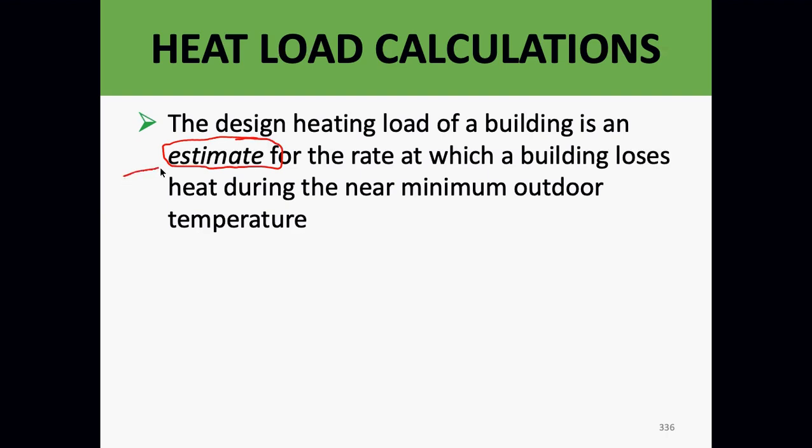But the key word is this is an estimate. That's why I don't care if you're off by a couple inches or even a foot. Okay, it's not going to make a difference in the grand scheme of things. Do I want you to be off 10 or 20 feet on a building length? No. But if you're off a couple inches for wall space or something like that, interior wall space, it really doesn't matter because it is an estimate.